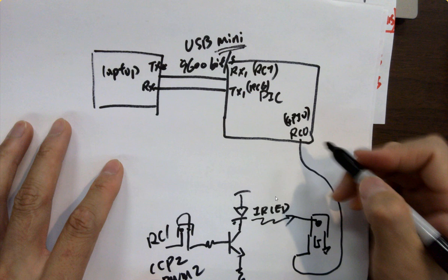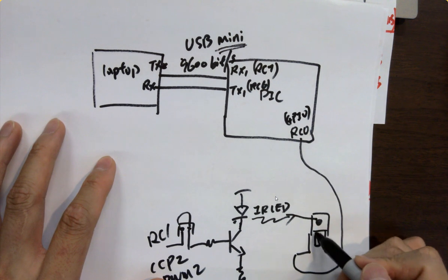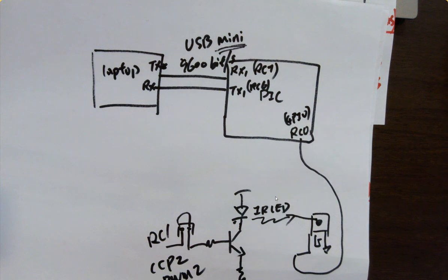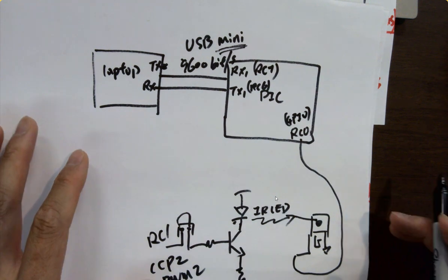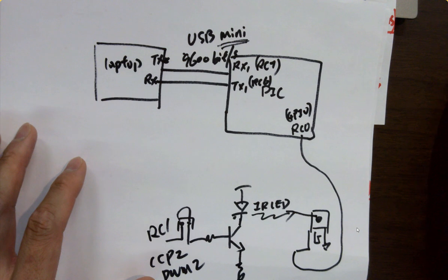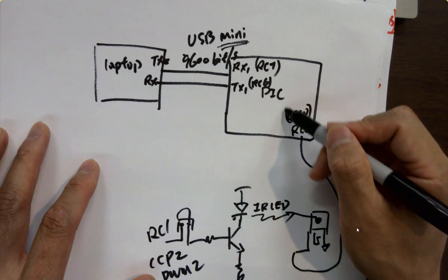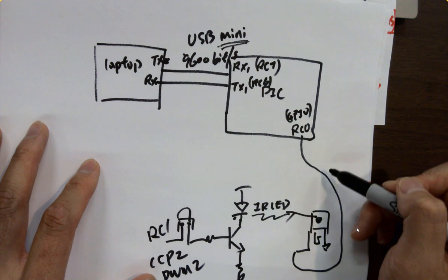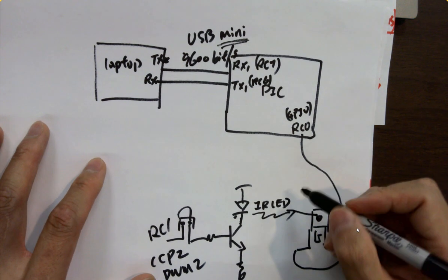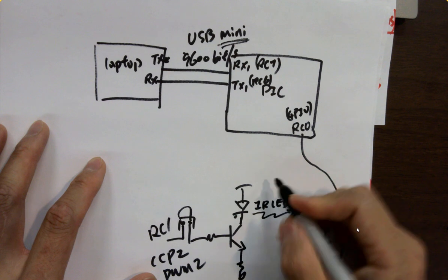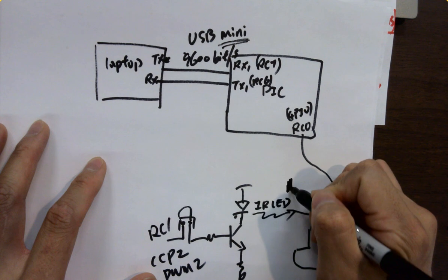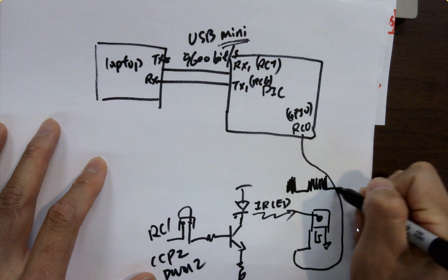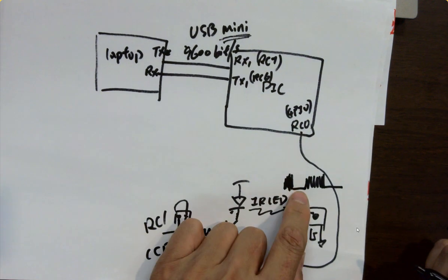Can you receive a digital signal with a certain protocol through a GPIO? Yes, but you have to hand code the protocol with certain time delays, because this doesn't have a digital block to automatically receive this data. For example, you have data like this, the light signal here. That's PWM.